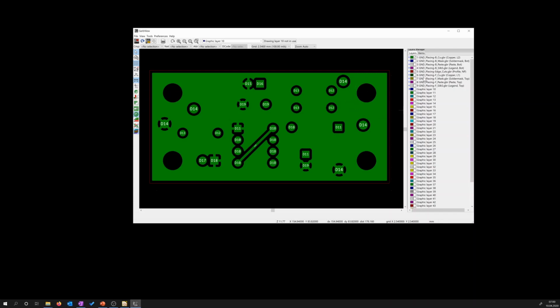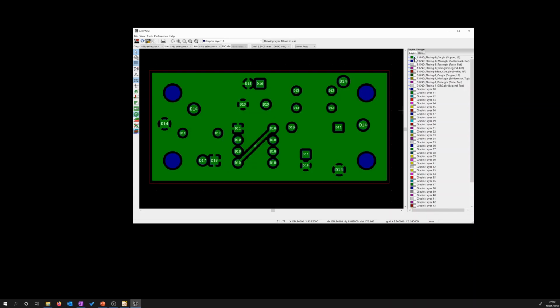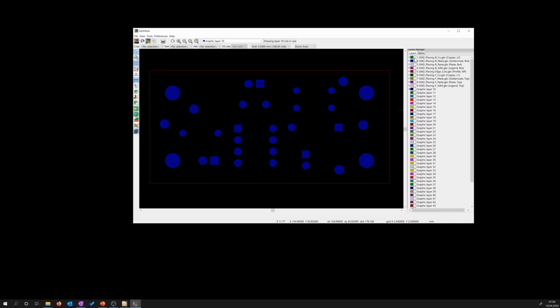So that's fine. Now interesting is the solder mask, or let's say the solder stop mask. And you see at these blue circles or squares, there's a window in the solder stop mask. So this means everywhere you have solder stop mask, and only these blue rectangles or these blue circles are left free.